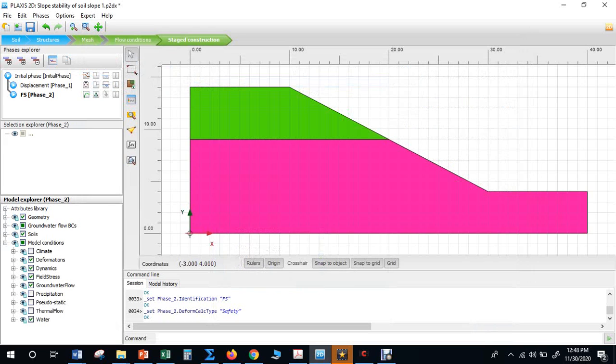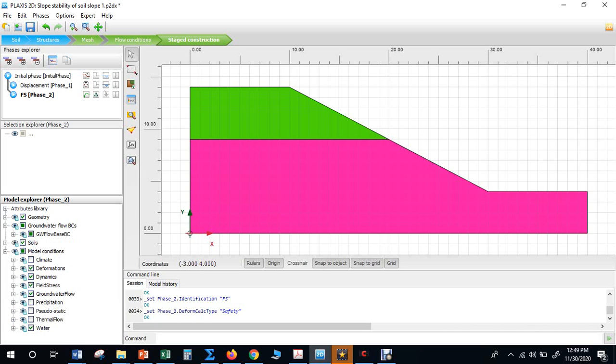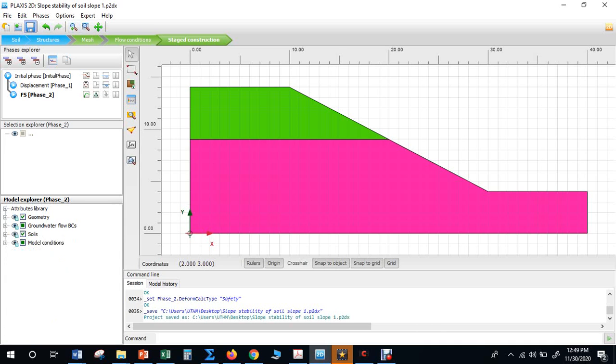If you see here, this is the infiltration, we set to 0.01. Now you can save, and then you can calculate.